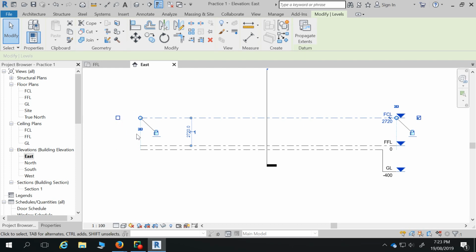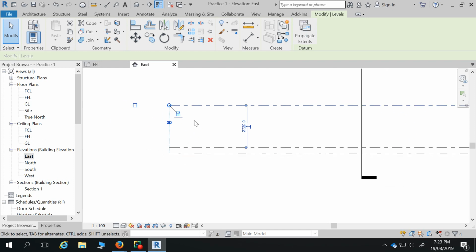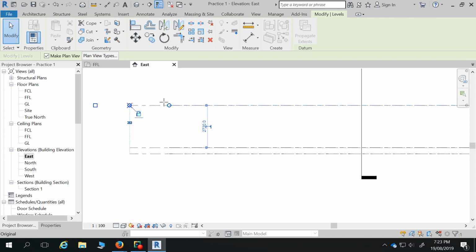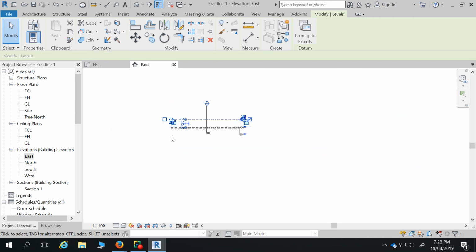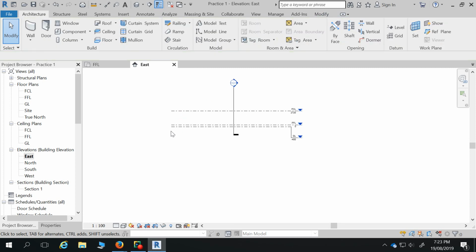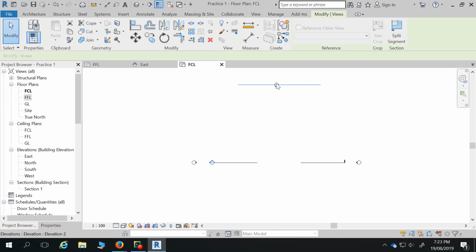The other thing that you might notice is when we've got this click, there's a little round circle at the end. That's like a little grip that allows us to pull these levels out and in, and that changes our view on this elevation. So what it's doing is, where the elevation's facing, giving us a left or right view. So if we draw in the middle of our elevation markers, we shouldn't need to change that because the view, say for the north elevation, is this line here.